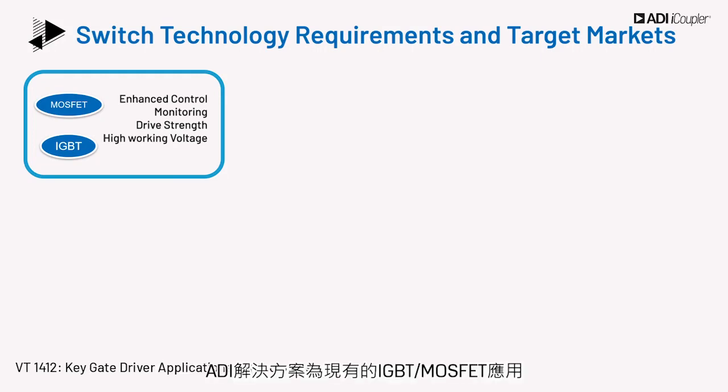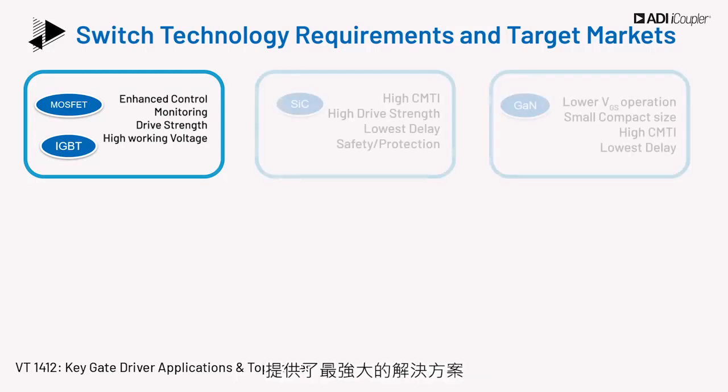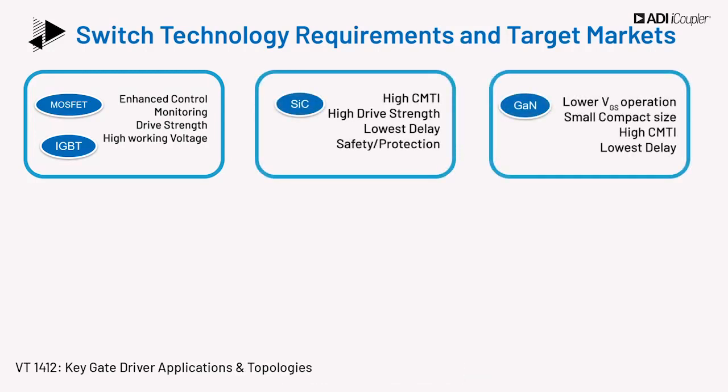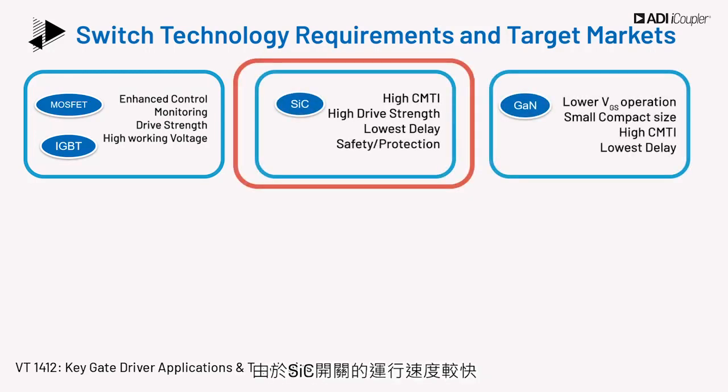ADI's solutions offer the highest performance for existing IGBT or MOSFET applications, while delivering the most robust solutions for emerging switch technologies such as SiC and GaN. The drive requirements of SiC switches are high CMTI and high drive strength of the drivers due to the faster operation of these switches.